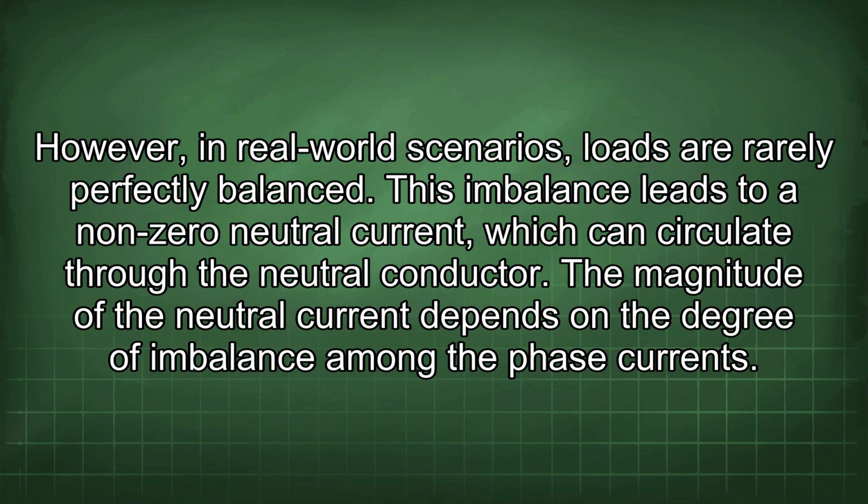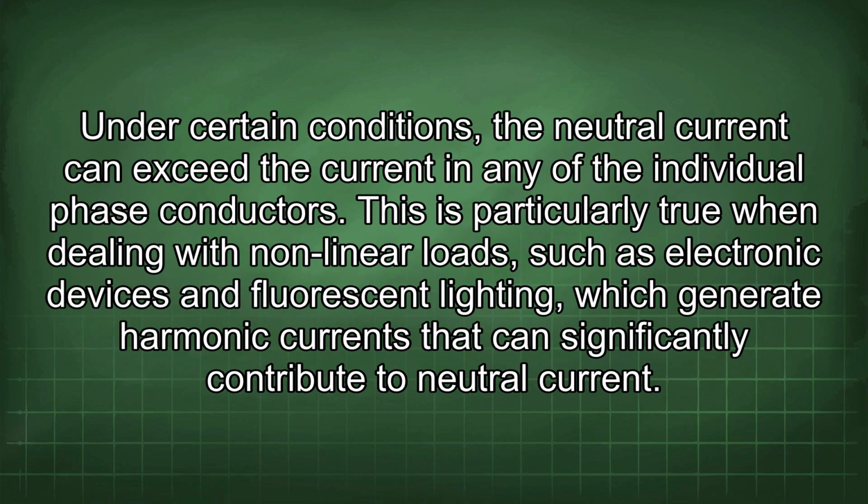The magnitude of the neutral current depends on the degree of imbalance among the phase currents. Under certain conditions, the neutral current can exceed the current in any of the individual phase conductors. This is particularly true when dealing with nonlinear loads such as electronic devices and fluorescent lighting, which generate harmonic currents that can significantly contribute to neutral current.